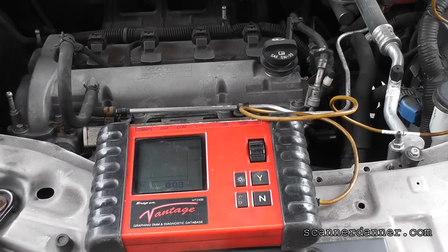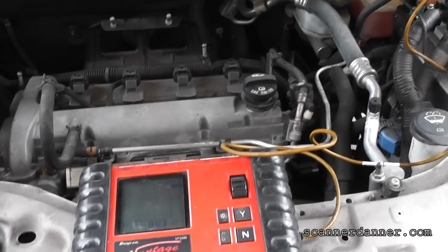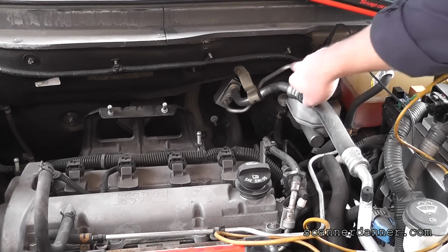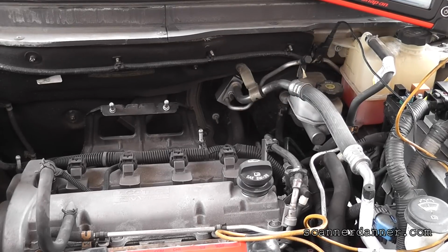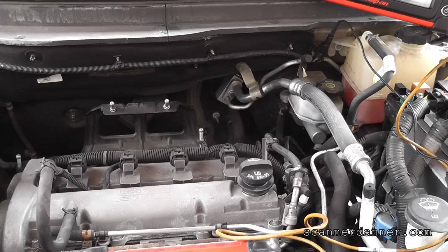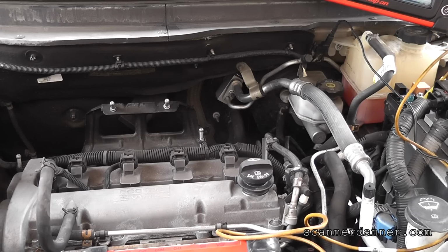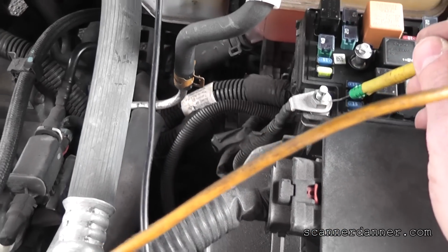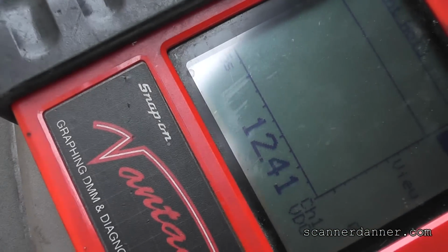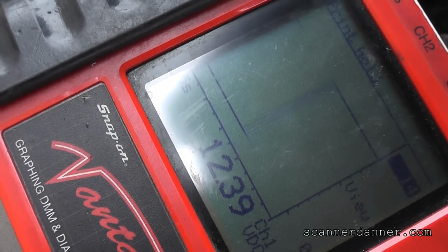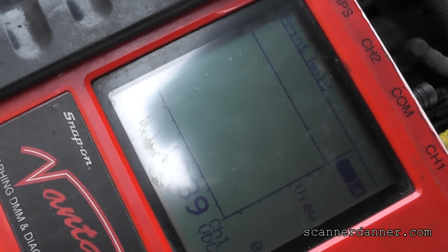So we're about to do a voltage measurement, and this measurement is going to be critical in direction. As I've stated many times, first thing we want to do is check our meter. I put my ground up here on the firewall because the battery is not easily accessible. Pop this little cover off this distribution box, and I'm just going to touch a known battery positive source, making sure that my meter is reading 12 volts. Take it off, put it back on. So what's that tell us about our ground location? Ground location is good, and we can rely on our meter.